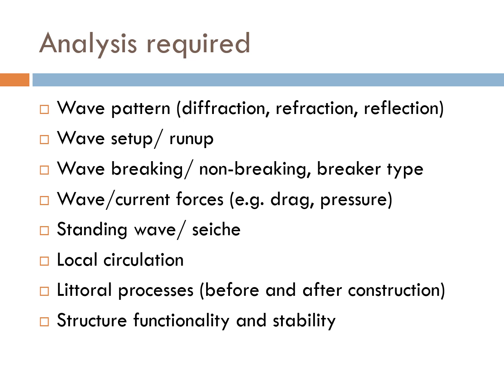Using the data obtained, some analysis that needs to be carried out will include analysis of the wave pattern, whether there's any diffraction, refraction, or reflection in the site area, wave setup and run up, wave breaking and breaker type, wave and current forces such as drag or pressure on the coastal structures. We will discuss more about this later on.